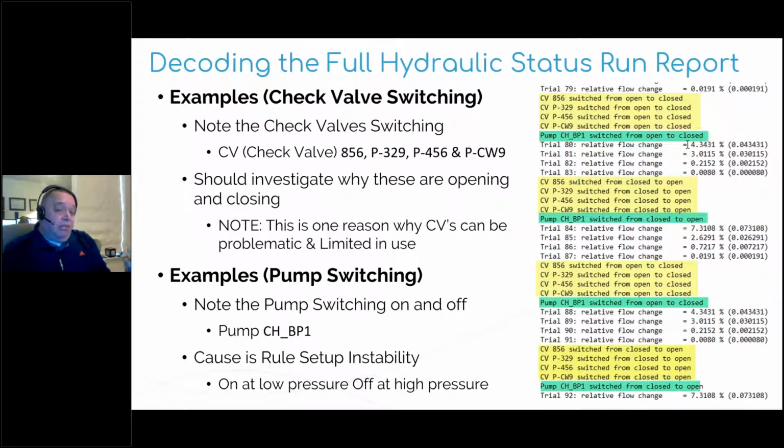If you had your off by either low pressure or high pressure, that's usually your off on a pressure-based control, or off by low flow in the discharge pipe, I at least could put a delay and they're not going to keep it from converging. But if they're both simple controls like this, hey, it's too low, I need to turn on. Oh, now it's too high, now I turn off, and then wait, now I turn on again, that's going to be unstable. That's kind of what's happening here.